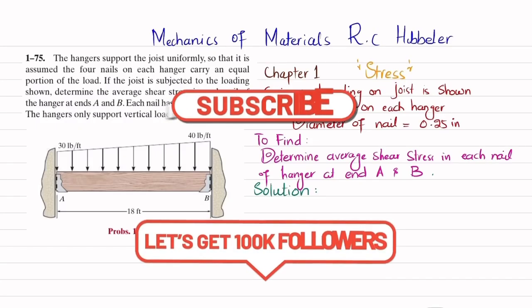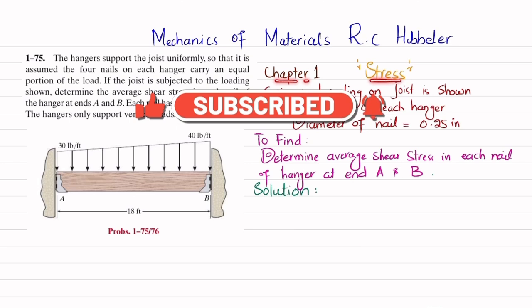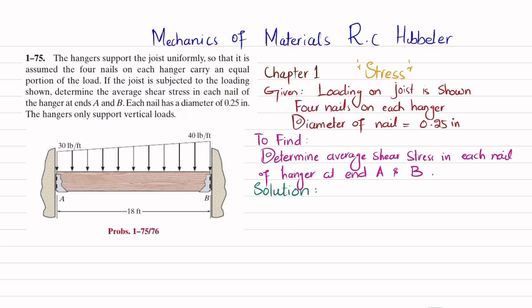Welcome back. In this video, we are going to solve problem 1-75 that is taken from chapter number 1, Stress, and the book name is Mechanics of Materials by RC Hibbeler. So the statement is: the hanger supports the joist uniformly so that it assumes the 4 nails on each hanger carry an equal portion of load. If the joist is subjected to the loading shown, determine the average shear stress in each nail of the hanger at A and B. Each nail has a diameter of 0.25 inch and the hanger only supports vertical load.